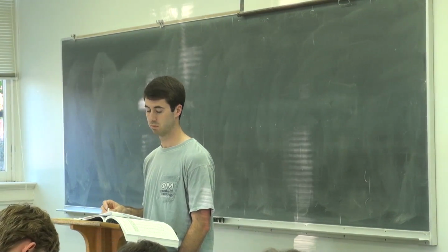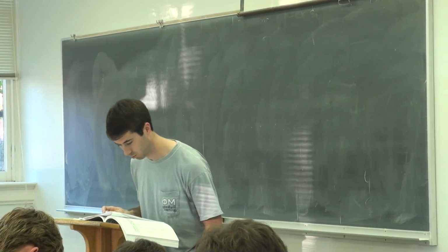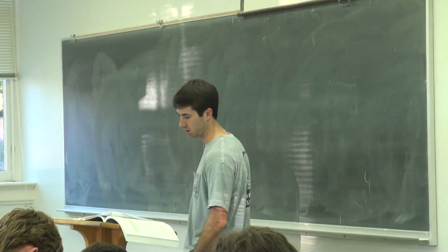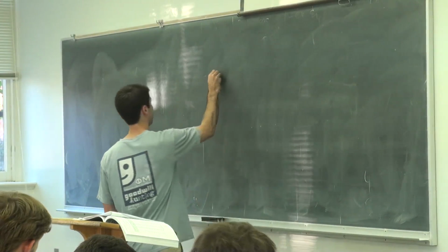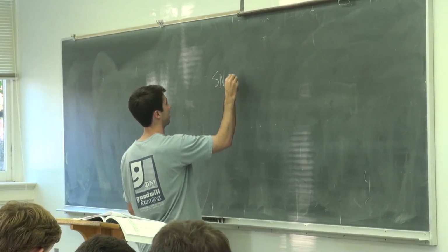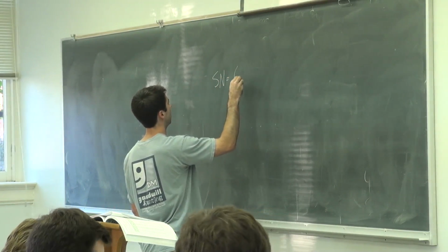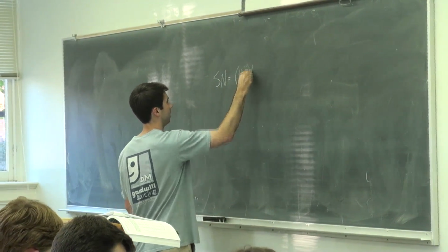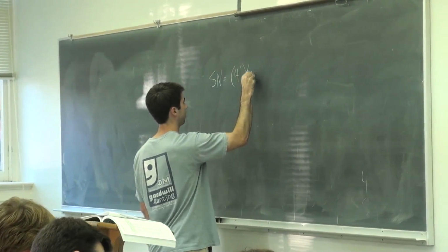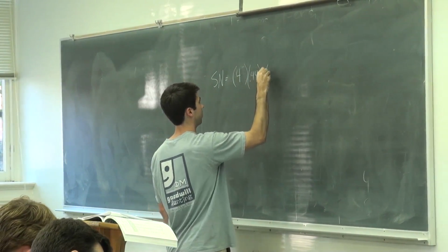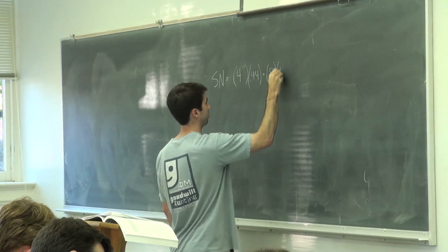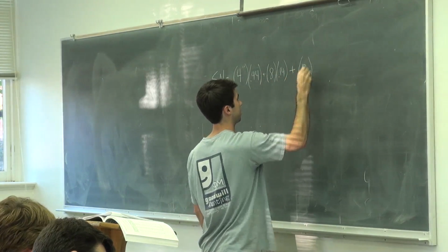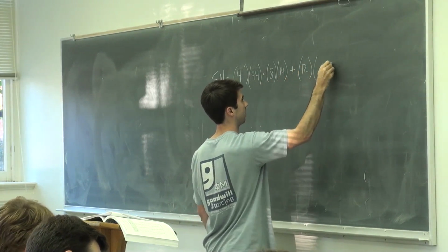Something less than 0.11. Yeah, 0.105 maybe. We'll go with that. All right, so at that point it becomes really easy to calculate. Our asphalt was 4 inches times 0.44, plus 8 inches times 0.14, plus 12 inches times 0.105.